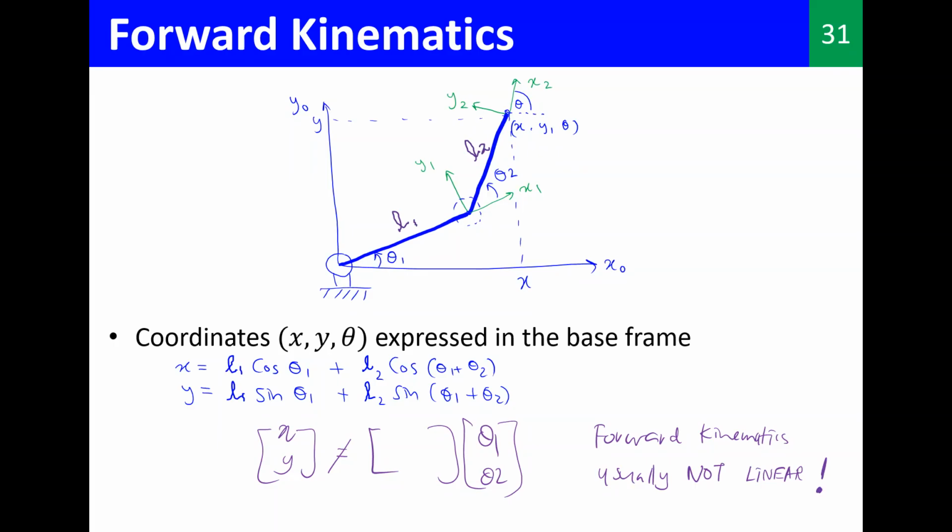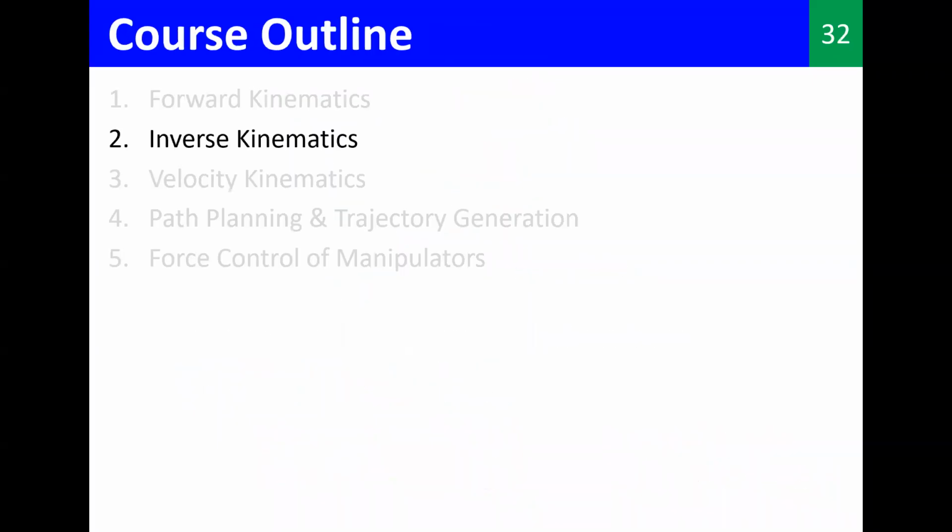Now, I think you know what forward kinematics is. So whatever the manipulator, let's say it's a SCARA manipulator or cylindrical, if somebody asks what it means by forward kinematics of a SCARA manipulator, it's basically about the mapping of these theta angles or the distances that you give to the joints and where the end effector is going to end up, right? But the most interesting and important is the opposite actually, right? That is called the inverse kinematics.